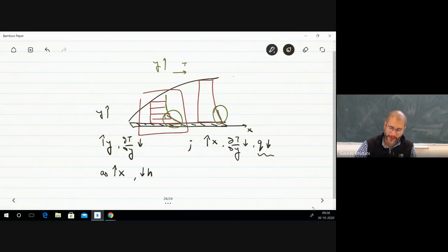So remember this idea that your heat transfer coefficient will decrease if you go further away from the leading edge of the solid surface. And similarly, your Q also decreases because of convection in this case. Okay. So it's again the same idea as fluid mechanics. As you go further from left to right, the skin friction coefficient reduces. In this case, your heat transfer coefficient reduces as you go from left to right in the plate.